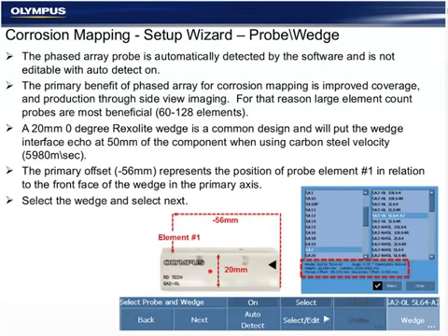So with this wedge in carbon steel, I can go from 0 to 50 millimeters without any obstructions from the second wedge echo. And these wedges come in different standoffs for moving that interference around strategically. The software needs to know the angle. Obviously, this is at 0 degrees, and not related to the focal laws, but the relationship of the first element to the face of the wedge, always referenced in a negative number.